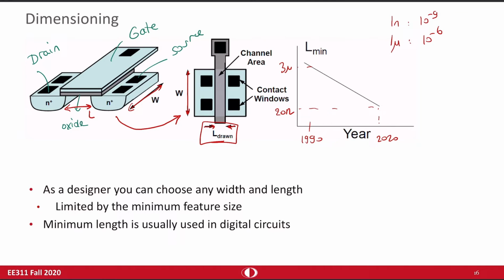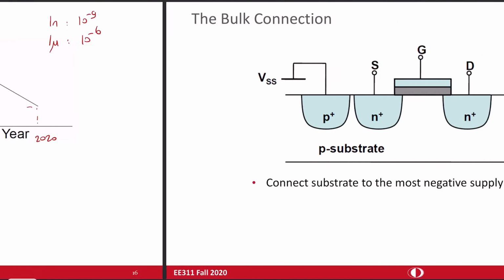So as a designer, on this transistor sizing, you only control transistor length and width. The other components like dielectric thickness, diffusion thickness in here, gate thickness, and so forth, you don't have any control, unfortunately, because the factory that's fabricating these devices defines them. Anyway, these are some general knowledge slides.